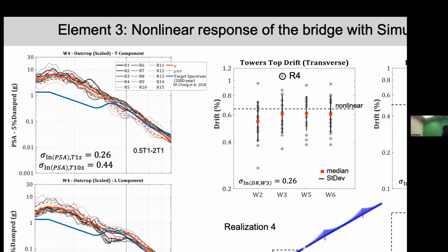And if you look at this WT that I'm showing here, the red line represents the yielded elements, and same thing for the deck here. So we're looking at a tower that has a fundamental period in plane of about 1 second, and here we're looking at the concrete pier. Even when our within-event variability is very low, which is something we're observing in these simulations, the actual motion that is transferred by these two piers to the deck itself is completely different, which is what we realize is driving the response of these decks and this big spread here in the response.